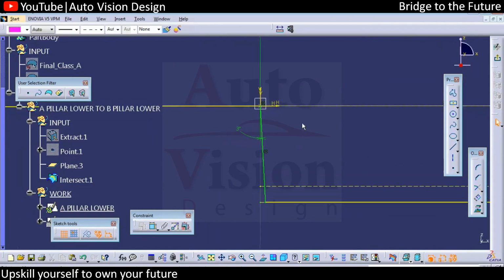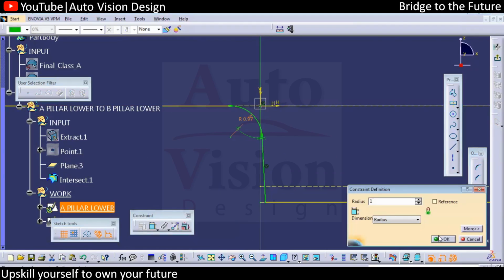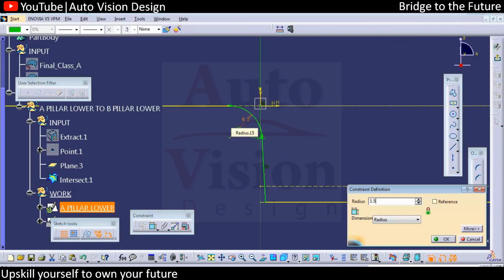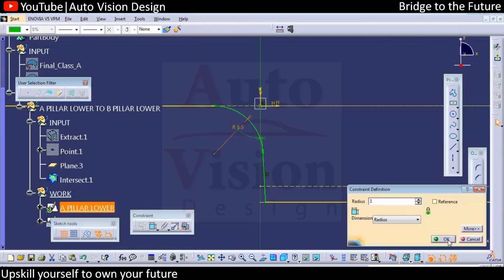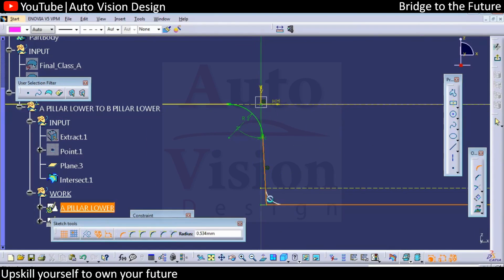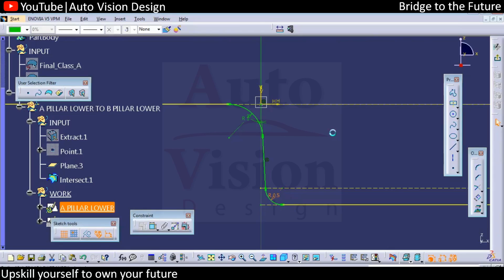Okay, so we need to add a fillet over here. So this becomes a class A. So we need to add something like a 1.5 fillet, because if you add more than 1.5, there will be more visible gap in between these two parts. Okay, so we'll add 1.4 as there is no head impact or something like that. So 1 to 1.4 is enough. Okay, then again in this area also we're going to have a fillet. So we can add 0.5 as this is an internal fillet we have. Okay, we can add this as 0.5.